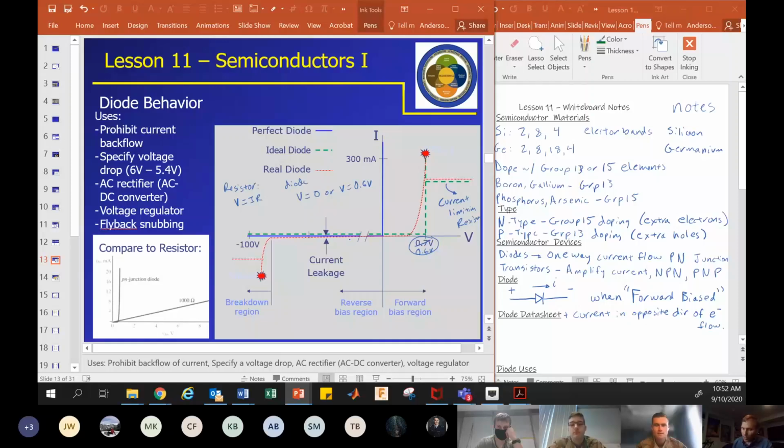Now for this type of stuff we're doing with our Arduino, where we're doing 5 volts, you can have 5 volts reverse bias a diode. You're not going to break it down. We'll see in a second. We'll look in the actual data sheet right now.